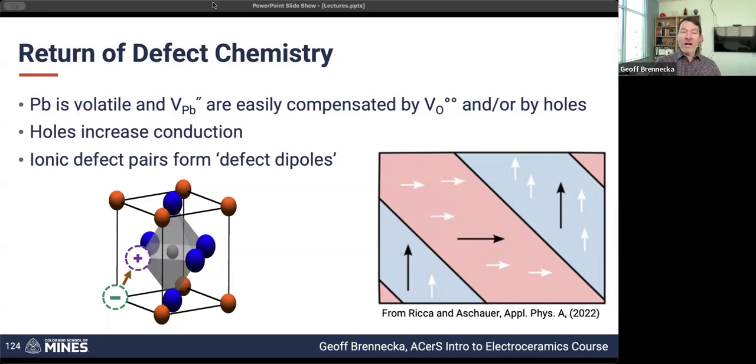But now, because these little white representations of the defect dipoles are basically baked into the ionic vacancies, they're going to be hard to move, because moving them actually requires a diffusion of vacancies that hop together. Flipping the dipole of a domain, so moving a domain wall, you're just shifting this ion up and down a little bit.